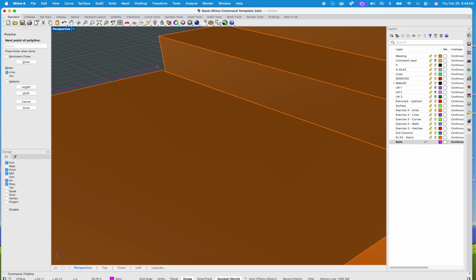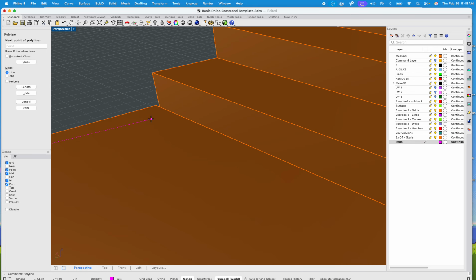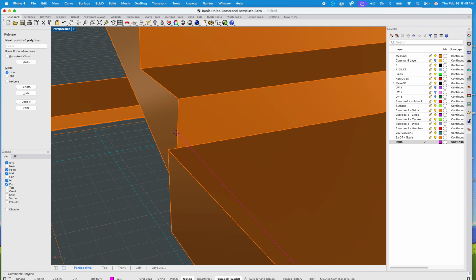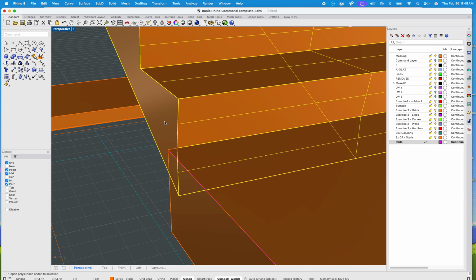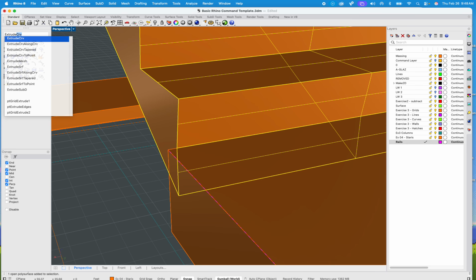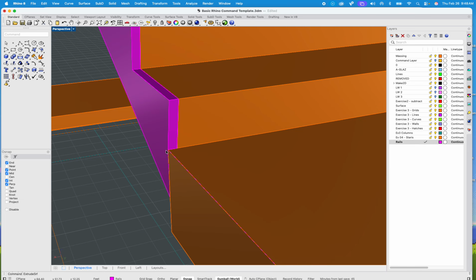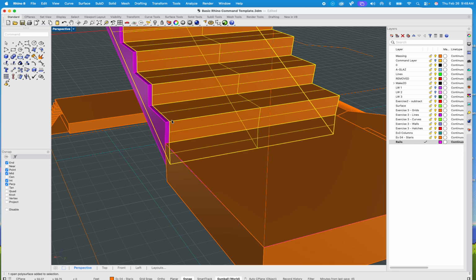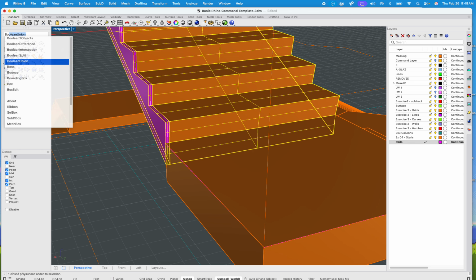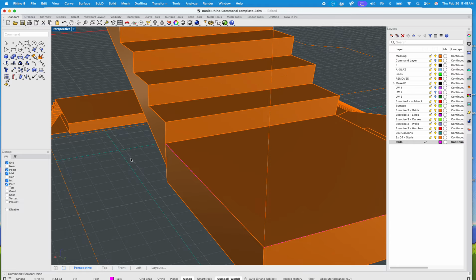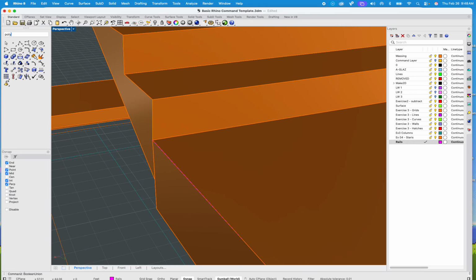See, this is where it's going to hurt me, right? I forgot to get that. Well, let's end it here and show you how to fix it. Enter. Can you guys guess? I can either move the face, this one, or extrude it. Honestly, both will work, right? So in my case, I'm just going to extrude. Oh, it's going to turn it into a new object, though. But not if I Boolean union them. Voila.